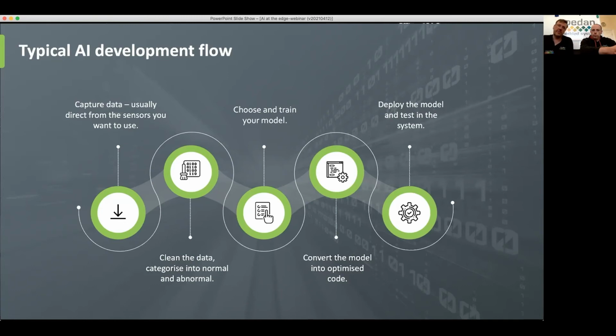So a lot of the time, the way that the data is captured on the embedded system is not quite the same as it is in real life. So maybe you've got to go back to the middle process in this and do some different quantization of your input data and some more learning. It's quite iterative, it's quite time consuming, but once it's done, you have a model that's trained and is good for purpose.